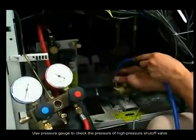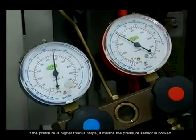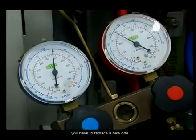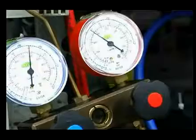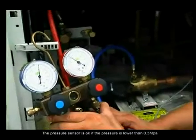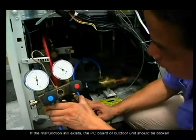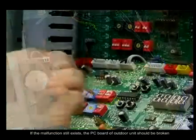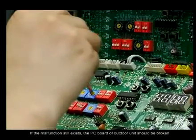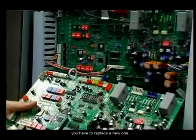If the pressure is higher than 0.3 megapascal, it means the pressure sensor is broken. You have to replace it with a new one. The pressure sensor is okay if the pressure is lower than 0.3 megapascal. If the malfunction still exists, the PC board of the outdoor unit should be broken. You have to replace it with a new one.